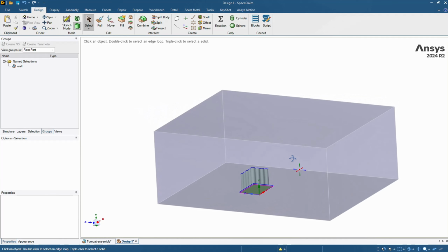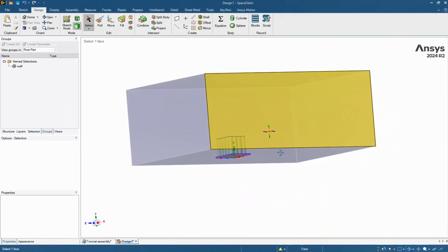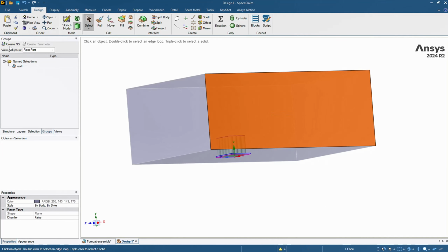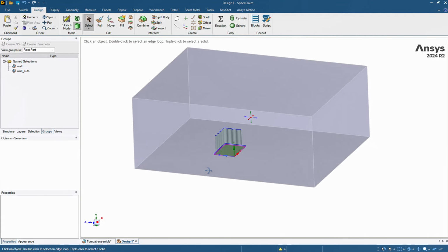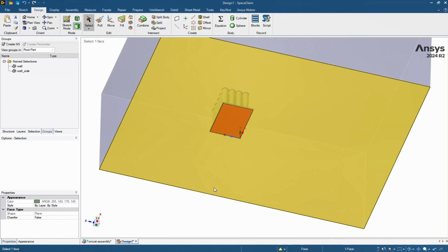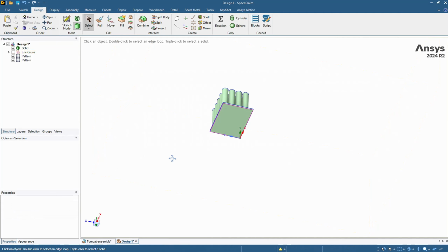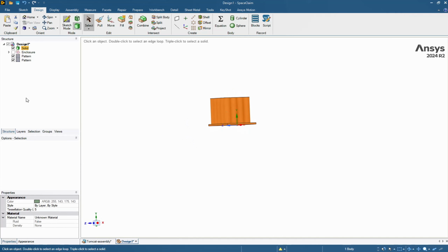That single act of naming turns a transient selection into a stable handle that the mesh, solver, boundary condition dialogues, and post-processing tools can all use. When selecting a volumetric part quickly, use the familiar Click, Expand, Click trick. Click once on a face to pick that face, click a second time to expand the selection to the contiguous patch or component, and click a third time to capture the entire body or volume. After that triple-click, you can hit Create NS and give the selection a name like Inlet Vol or Heater Block Vol.